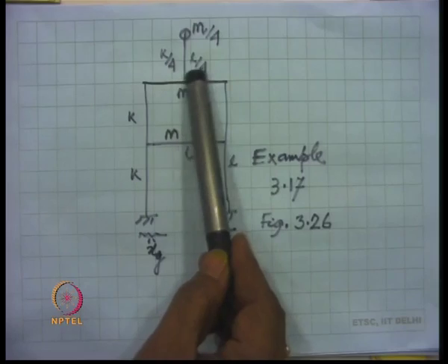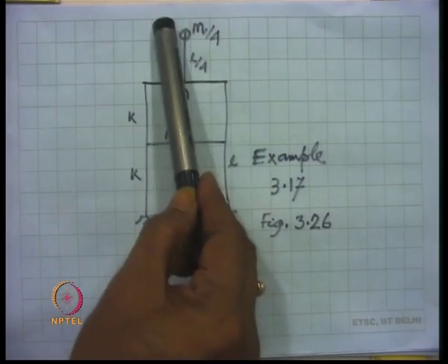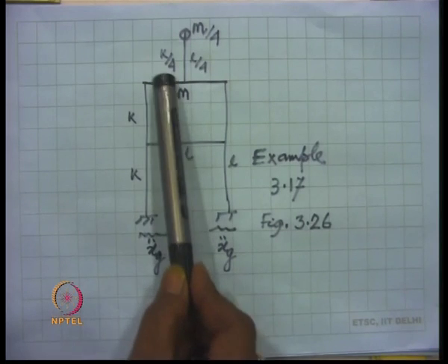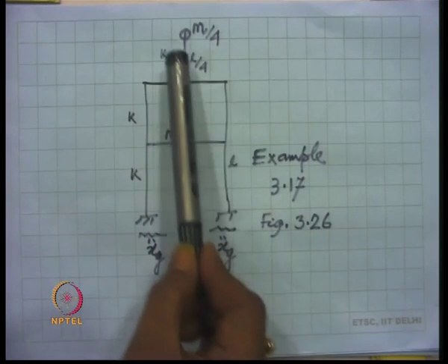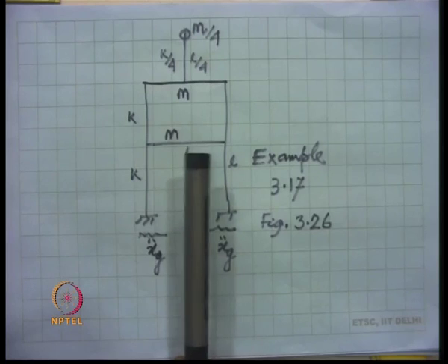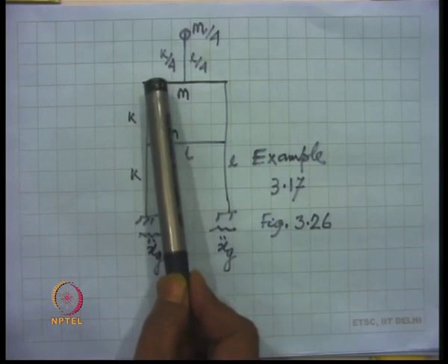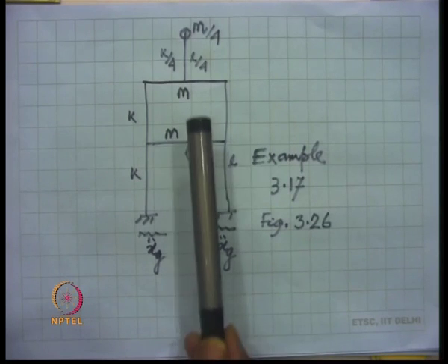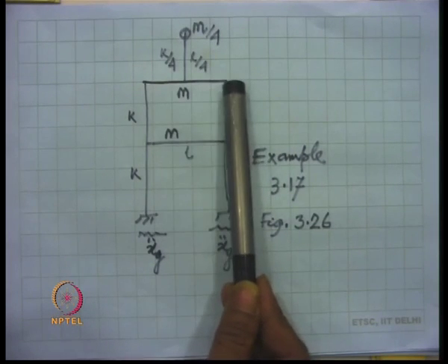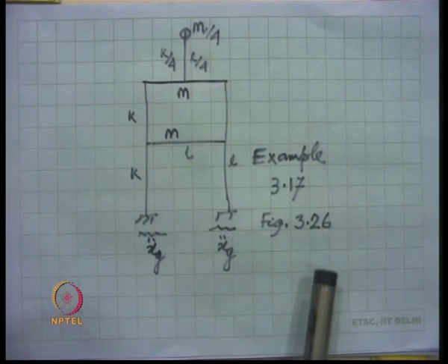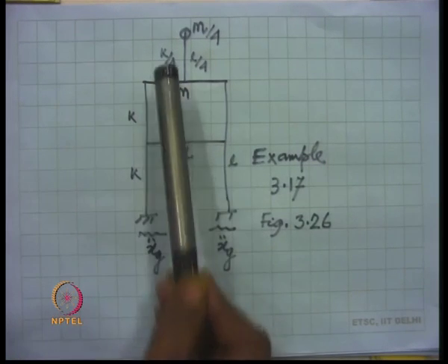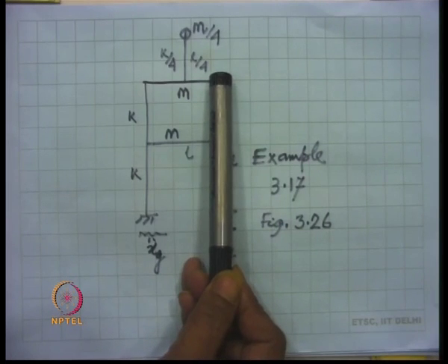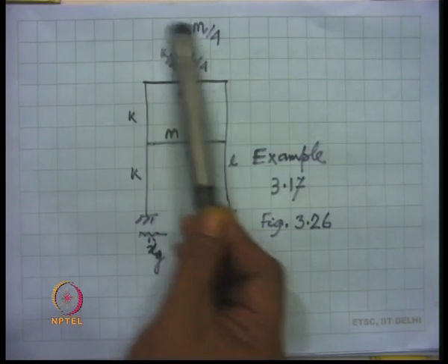However, one can have a structure which is not a single degree of freedom system like this. In fact, there could be a piping system in which there could be 2, 3, 4 supports, and in that case at all the supports we can assume that the same time history of absolute acceleration would be acting, for which we have obtained the response spectrum, and then carry out the usual response spectrum method of analysis for the piping system.